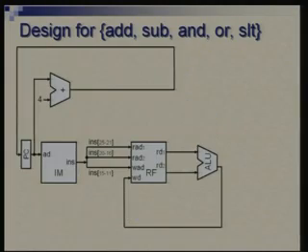Since our approach is the same, that we are trying to do the whole thing in a single cycle and the broad components have been identified, we will approach the same design point at the end. So this is what we had as the starting point even yesterday: for doing add and subtract operations you need the PC to supply the instruction address.